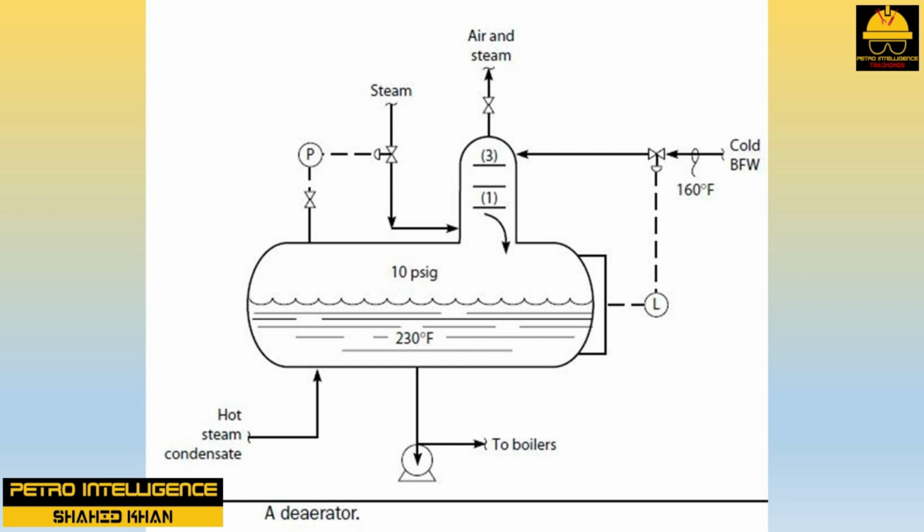The reduction in the deaerator pressure increased the volume of steam flow through the bottom tray of the stripping tower. Why? According to the ideal gas law, volume is inversely proportional to pressure. As the pressure of the flowing steam declined, the steam's volume increased. The larger volume of steam flow resulted in a higher vapor velocity to the stripper trays 1 through 3. This caused the bottom stripper tray to flood.